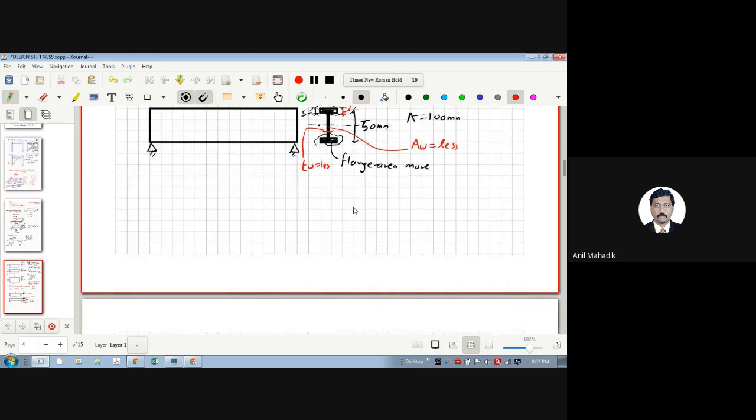So there is one more choice. Now you can understand by looking at the moment of inertia. The main property in any steel structure section is the moment of inertia. There is one more choice by which you can develop that section. You can have an I section, and you can also add angles to it. Let's say this is one plate, then I am putting an angle over here, and then an angle over here.